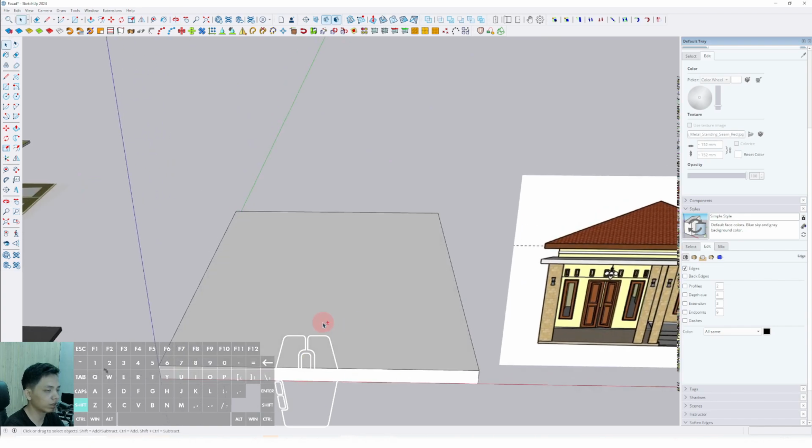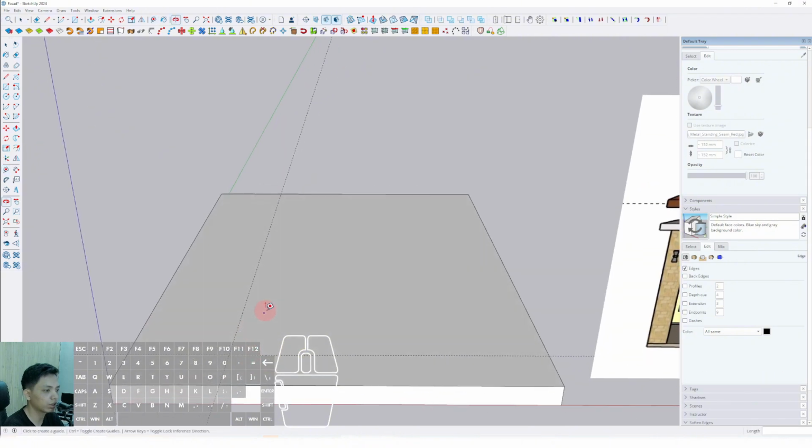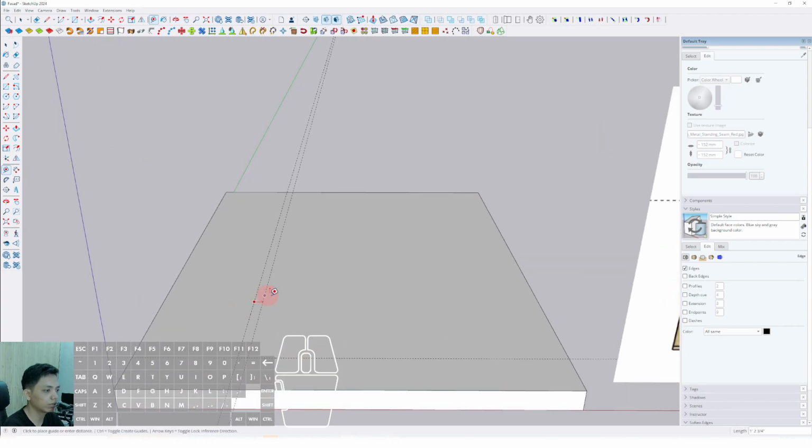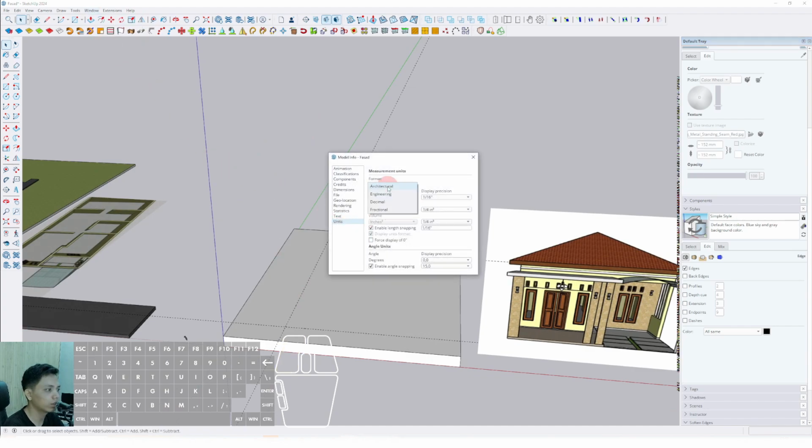I will apply these materials and objects on my design version. Okay, first of all I have to set the dimension using the tape measure tool. I've set it at any position over there and in this position. Then we can drag to another position around 7 meters. Okay, sorry, I have to remodel. I have to set the units with a decimal, millimeter, meter, and cubic meter.